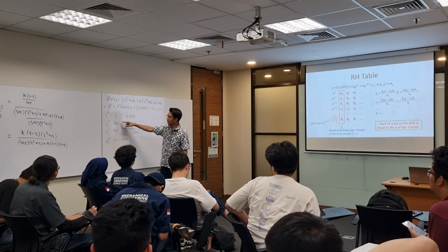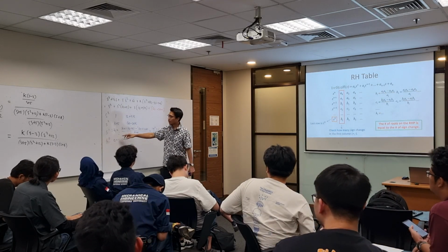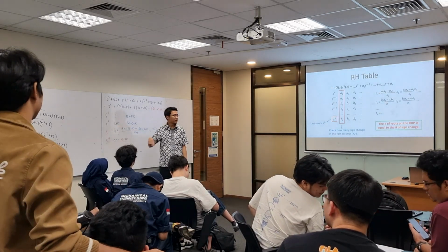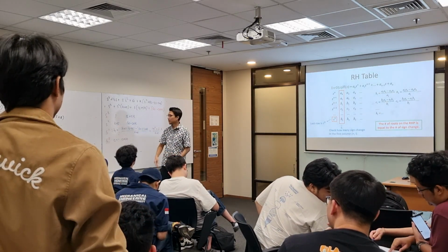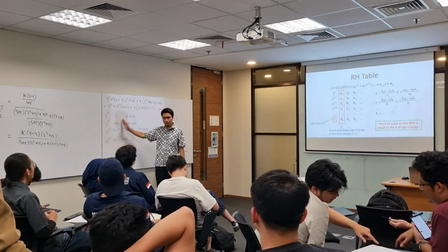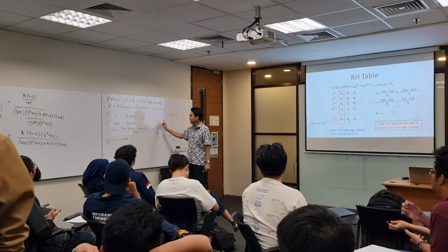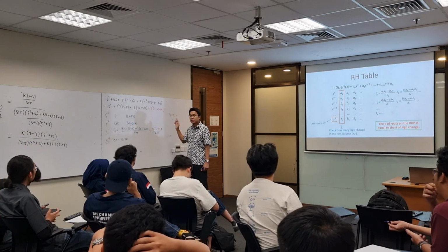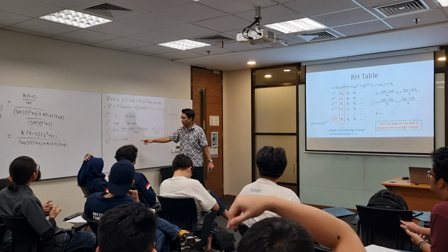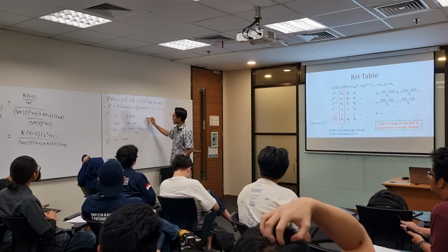So when we derive this, we have B1 equal to this, and this is the C1. We want the first column to be positive, because K must be positive in that case. What's K to make this positive? At least 0, right? To make this positive, K must be greater than 0. It cannot be 0. Also over here, greater than 0. So any K greater than 0 will do.